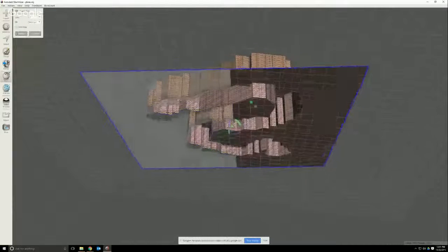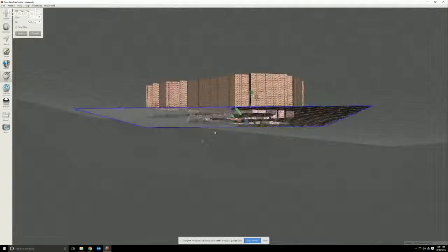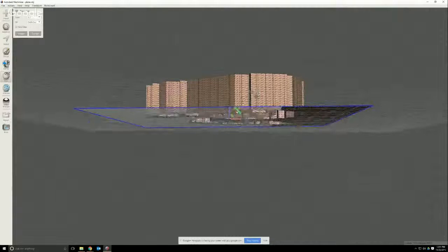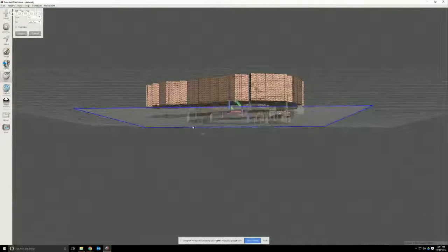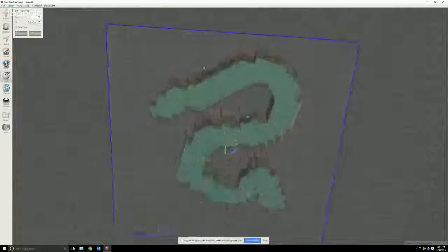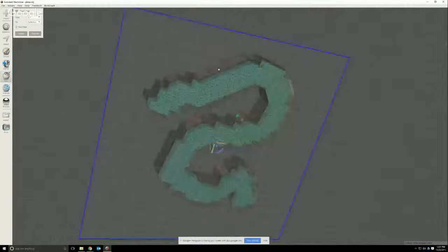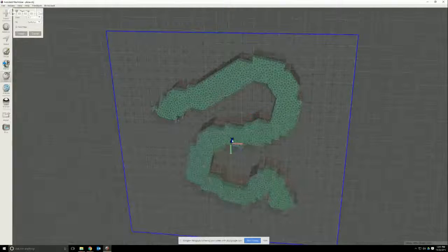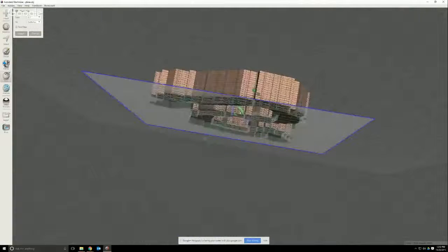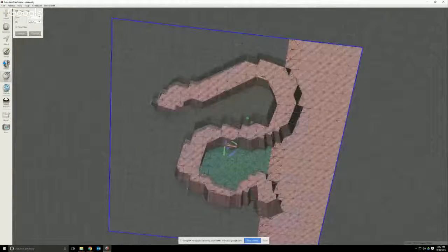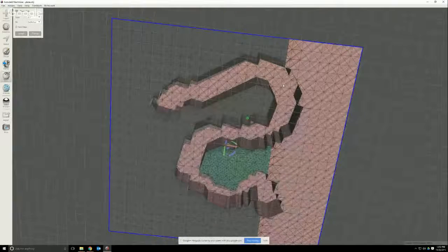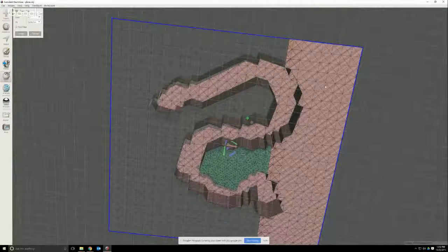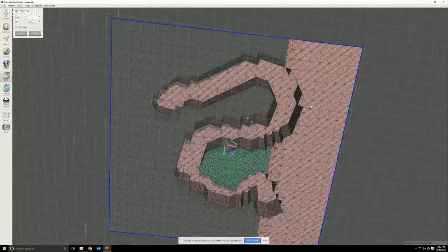Now, one thing with the Plane Cut tool: if it's off even a little bit like this and we click Accept, you're still going to get the same effect, because it needs to cut an absolute complete outline. You see the preview here shows we're creating a new face group of solid triangles. As I tilt it a bit right here, now you see the preview has no solid area, because our angle has prevented a complete outline from being cut.